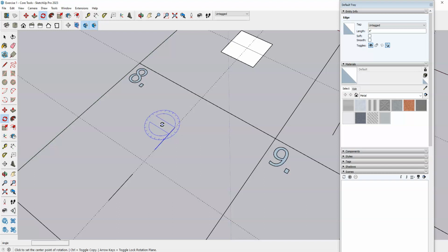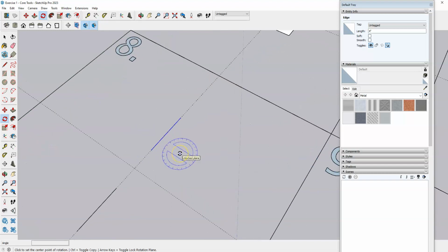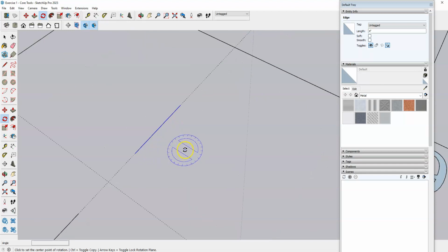You'll choose a starting point, and that will become the point that stays in place while everything else rotates around it. So you'll choose your starting point and then specify a direction to be like your 0 angle, and then you'll be able to rotate the object the way that you want. So for this first one, we're told rotate the first line 90 degrees starting from the midpoint.